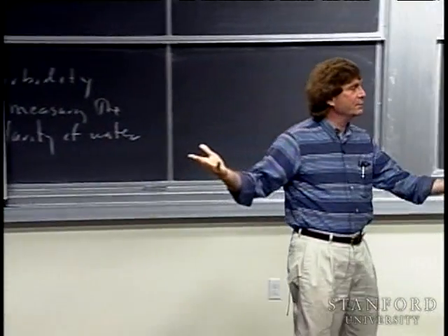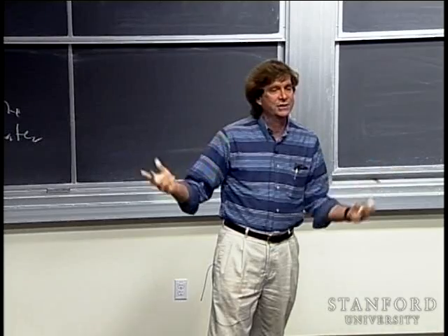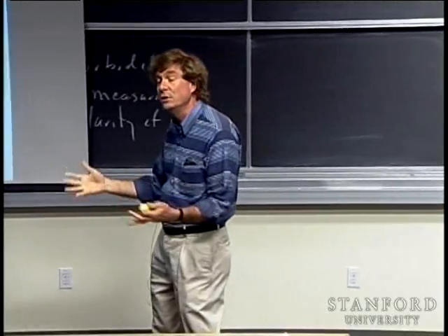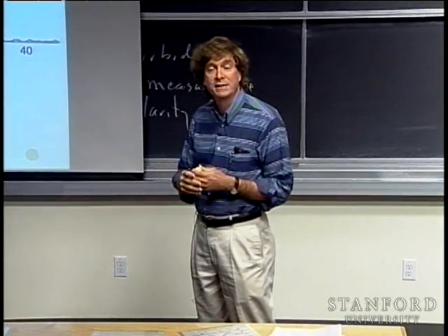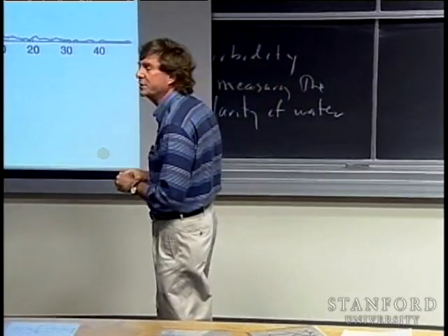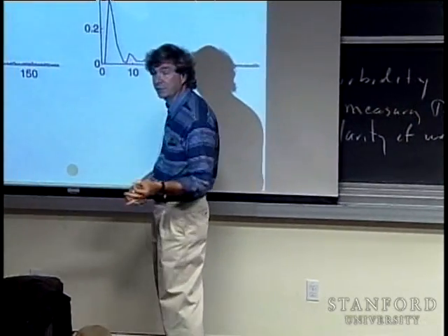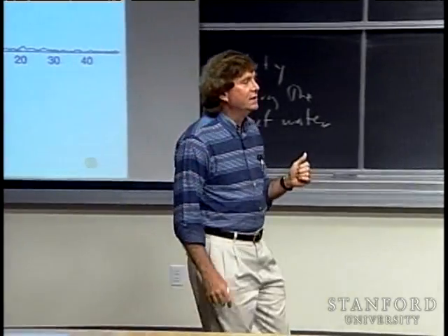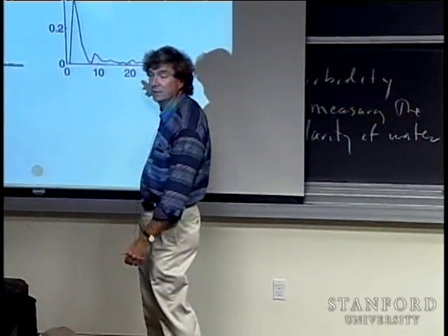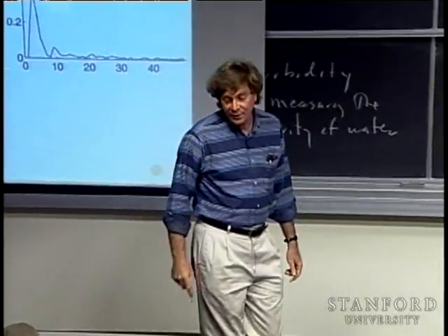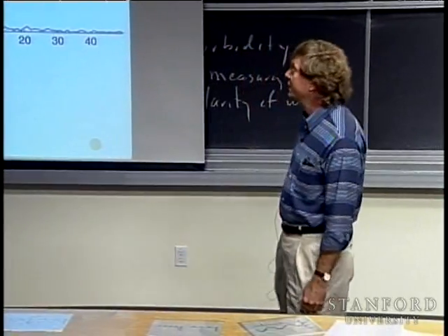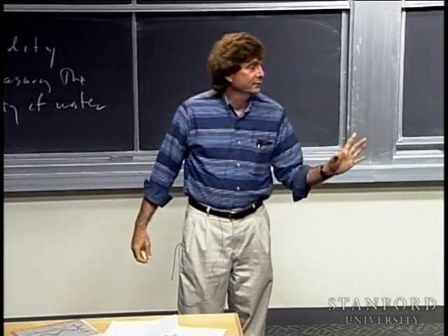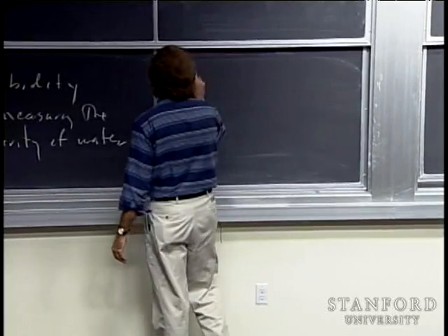Just as in the case of Fourier series, the high harmonics are causing the signal to oscillate quickly. The same thing holds with the Fourier transform, although the spectrum is continuous; this is the same principle. High frequencies are causing sharp, rapid oscillations. So what do you want to do to smooth it? The natural thing is to just kill off the high frequencies. How do you do that? The simplest way is by multiplying by a rectangle function in the frequency domain.